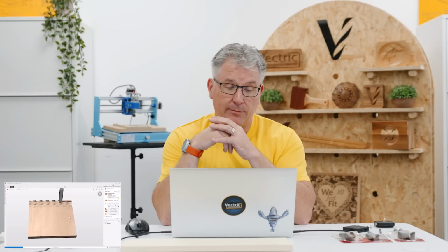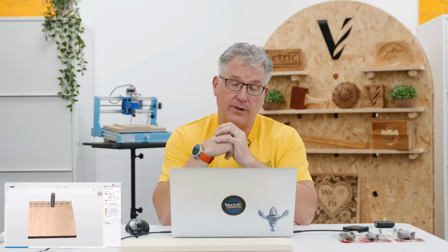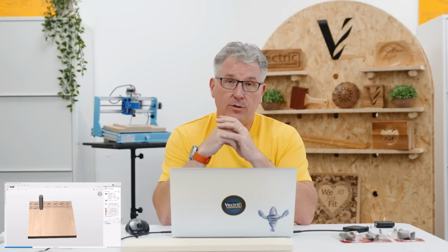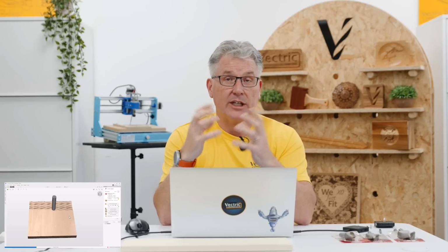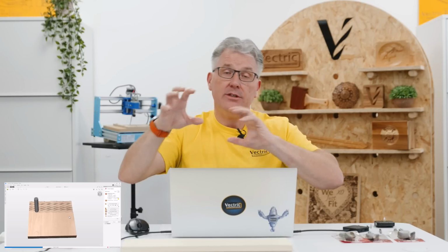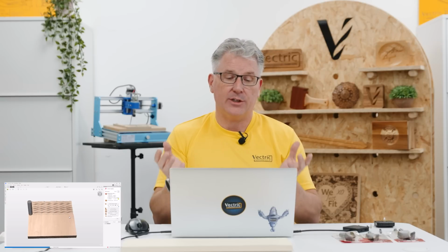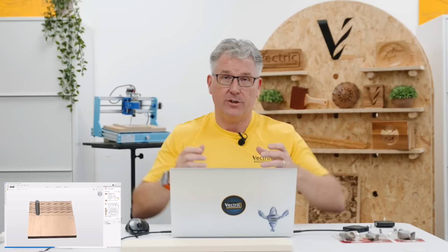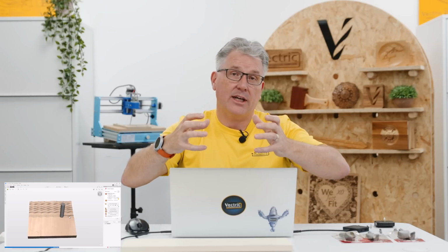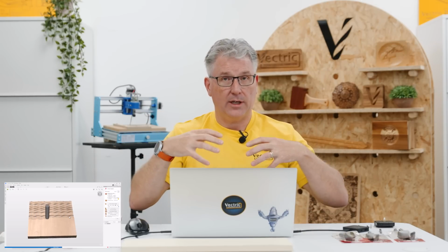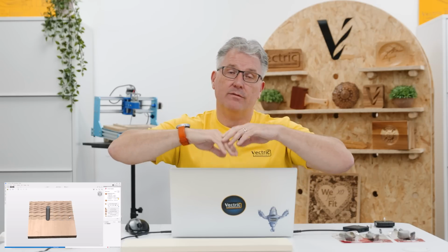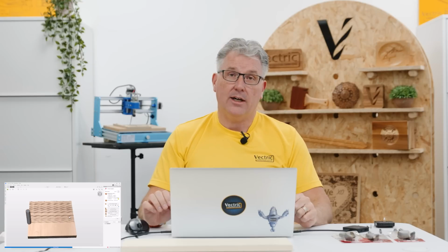Now, one of the things I forgot to mention earlier when we were creating the vectors for this texture toolpath is that you could actually choose a vector shape like a circle and create those vectors right inside that shape, or between two different shapes. So if you want to isolate those, you can. That's a great technique if you're going to put a texture like this in the background of a sign where you're going to be choosing the border, maybe some middle text that you want it to avoid. Then you can go ahead and do that and you'll only get vectors created in between the vectors that you have selected. That's a great use of the texture toolpath.